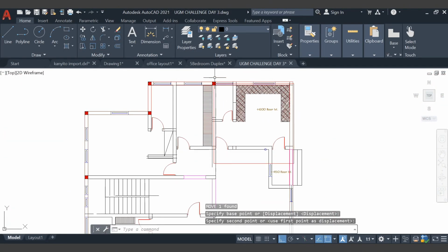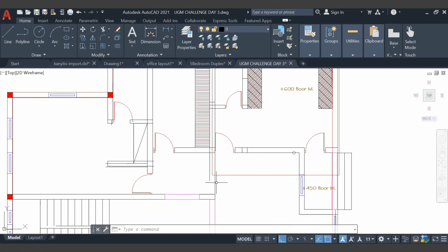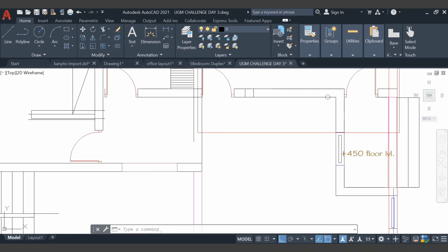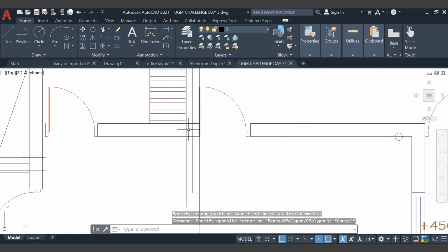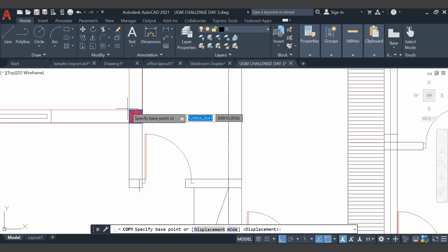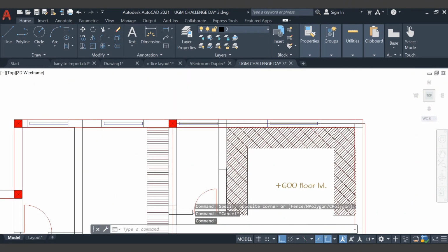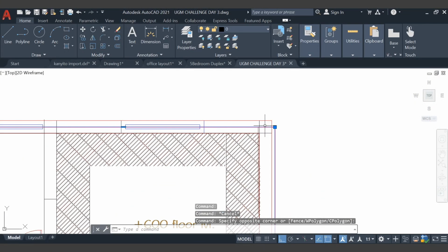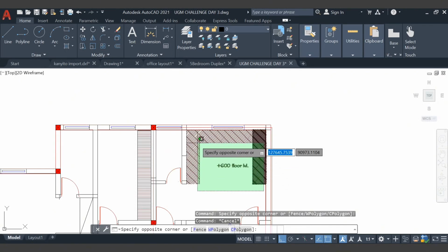So 5.5 meters from this side would give me here, but this falls in between a lobby. Okay, it falls right into the lobby, so it's best I place the column over here. So I can do the same on the other side, because this is 5.5 meters, so the column placement would work.